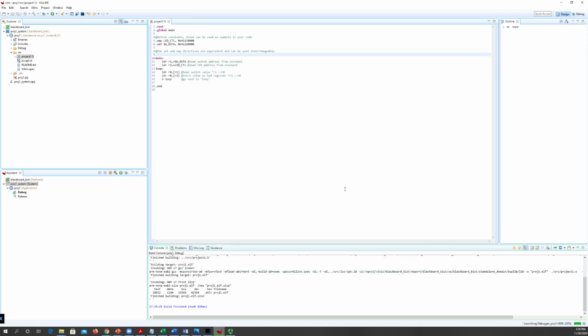And what that's going to do is transfer both the hardware definition and the software to the board. And now you can't really see this, but the board just finished programming. You saw that window pop up. And now I'm activating the slide switches, and every time I push a slide switch on my Blackboard up, the corresponding LED turns on. And that's really all there is for the first part of the project.